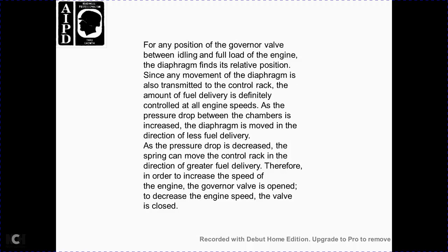For any position of the governor valve, from idling to full load of the engine, the diaphragm plunger takes a relative position. The movement of the diaphragm also transmits to the control rack the amount of fuel delivery, definitely controlling all engine speeds.